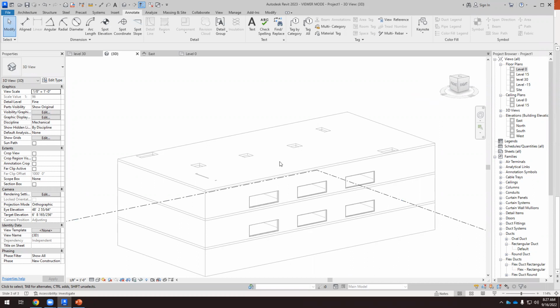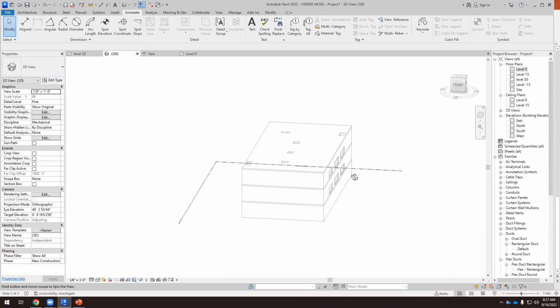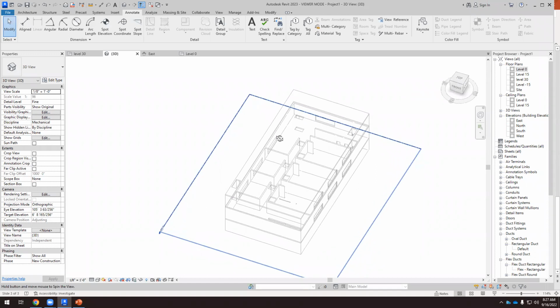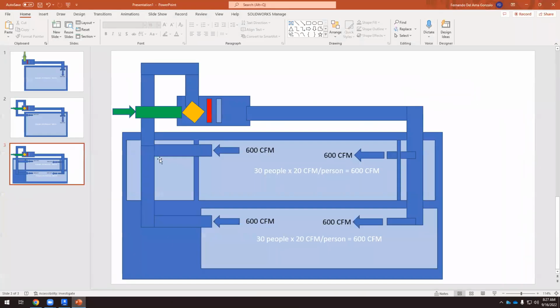This connected to the classrooms, I don't know. I would use this one as the main vertical duct to get to all the classrooms of that building. Okay, so I'm going to use this one for the vertical pipes from the air handling unit. This is not accurate, because here I have a duct for the supply and another duct for the return. That means I need 2 shafts. So I'm going to try to place both ducts in the same shaft.